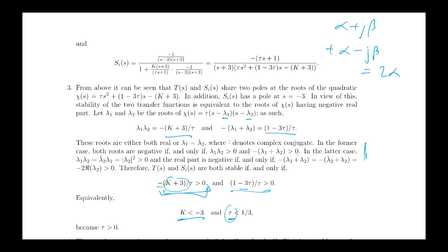That result has followed just by analysing the zeros of the denominator of the transfer function. They are the poles. It's the characteristics of the poles that determine whether the transfer function is stable or unstable. For it to be stable, all of the poles have to be strictly in the left half plane.